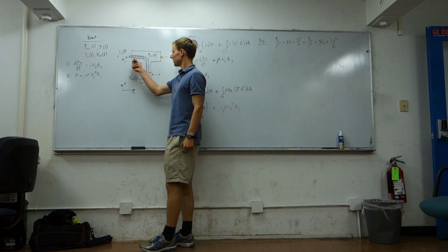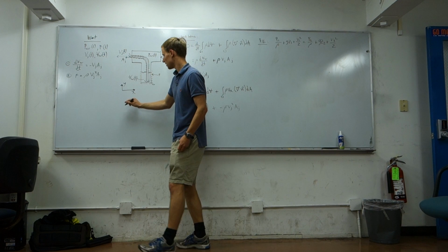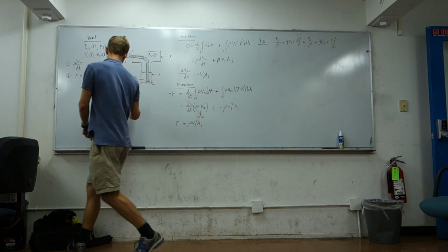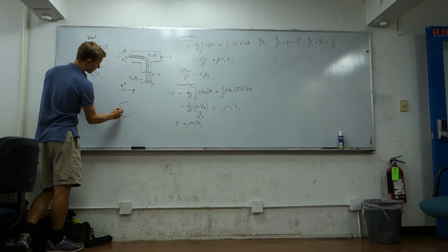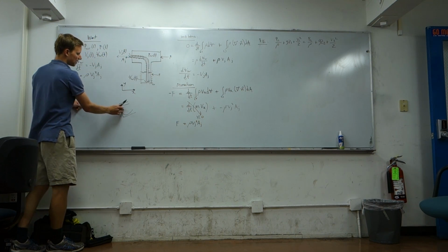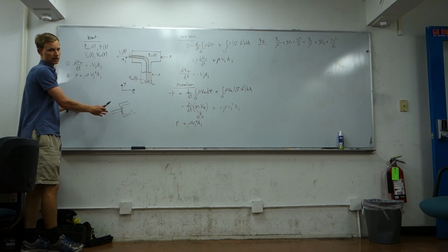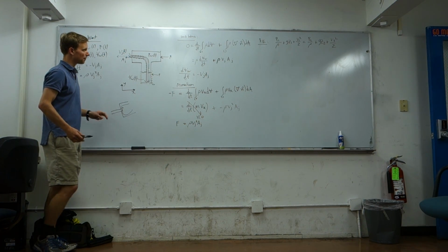Turns out that in the nozzle here, we have a huge amount of turbulence where we have a contraction. The nozzle just is simply a chamber which is restricted down into a lower area. So this region in here requires some sharp bends and some turbulent eddies that form. And we can't neglect that, the viscous nature of this flow here. So we're going to try to account for this in a second. Just keep that in mind.